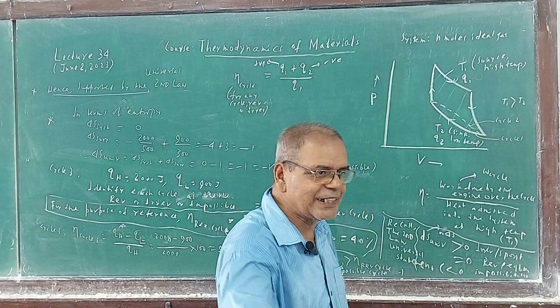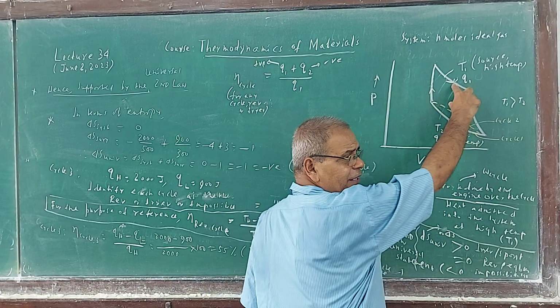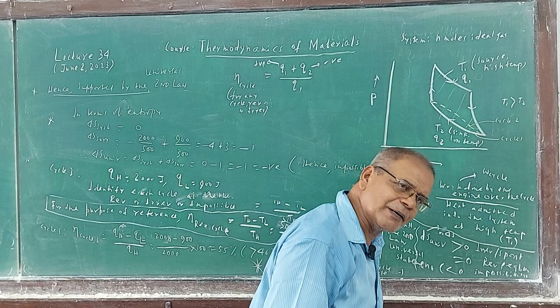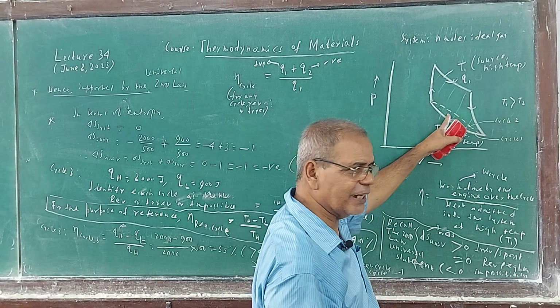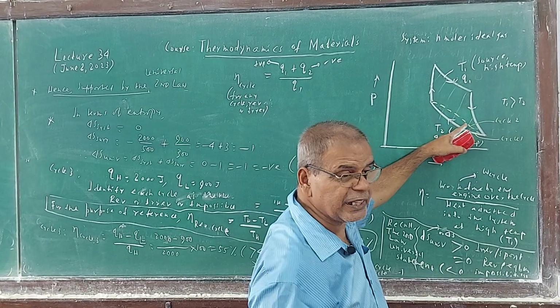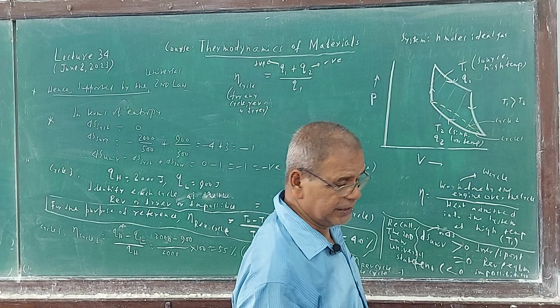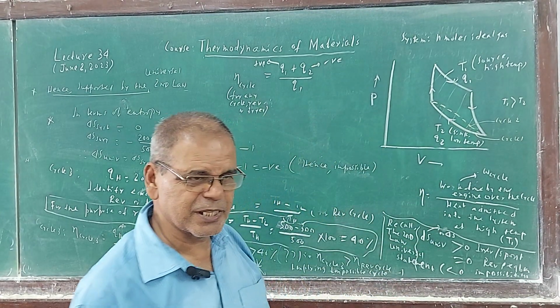Work done over the cycle is the enclosed area. The enclosed part is now reduced compared to the reversible cycle. See clearly, this is the figure, and you should also have the idea that area under the curve, compression, etc. is heat rejection. So you see efficiency has been reduced.